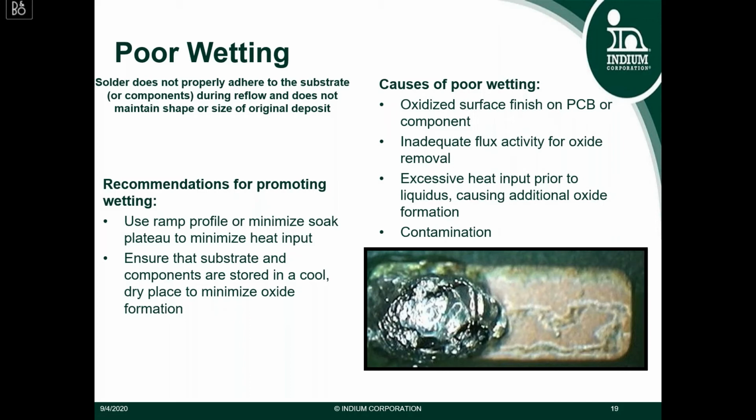Some causes of poor wetting, as we mentioned in the last slide: oxidation of your surface finish on the PCB or oxidation on your component. The flux activity level not being strong enough to properly remove oxides.